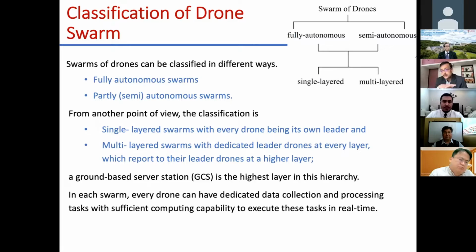Of course, security is also compromised in the case of multi-layered, because if this one master drone is killed, in case of defense usage, then these four drones will be killed automatically. They will not be able to communicate with other members of the swarm. Therefore this multi-layered drone is, however, relatively robust for the communication. Robust in communication, not in survival. In case of communication, they are robust, but in case of defense related applications or other long distance missions, multi-layered drones are not preferred.